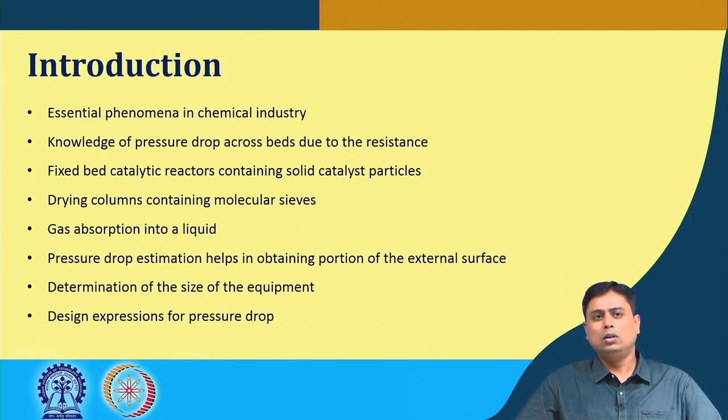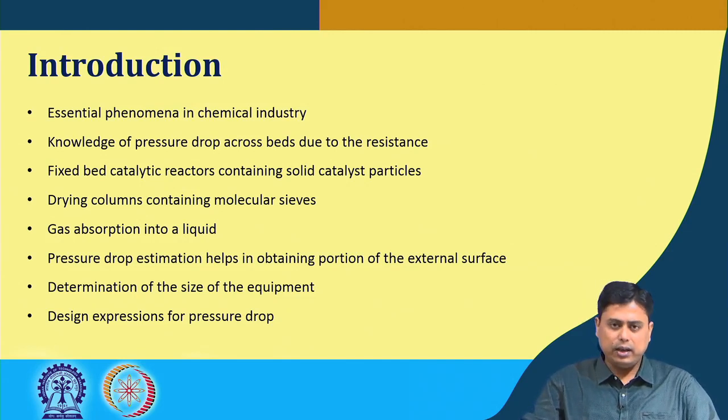Now this pressure drop estimation helps us get an idea of how much external surface is available. In the case of a solid catalyst, the reaction can happen on the solid surfaces, the adsorption can happen, and this solid surface basically dictates how much resistance there will be as well, through the available surface area.